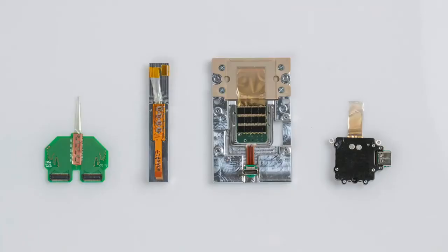This is a photo of some of the prototypes that we've gone through over that time. We started on the far left. That's an entirely passive board that has 64 electrodes on it and connects to connectors that go to big external amplifiers. And then we added integrated electronics with our first custom chip. That's also 64 channels. And then there was a big leap to the device that Elon showed a photo of earlier. That has 3,072 electrodes in a fully implantable package with just a USB-C port coming out. And then we took a step back in channel count, because remember, we have to optimize safety, longevity, and bandwidth all together. And so in order to optimize some of those other things, we moved to an easier to manufacture system that has 1,536 channels and a USB-C port. And those last two are the focus of the paper that we released today.